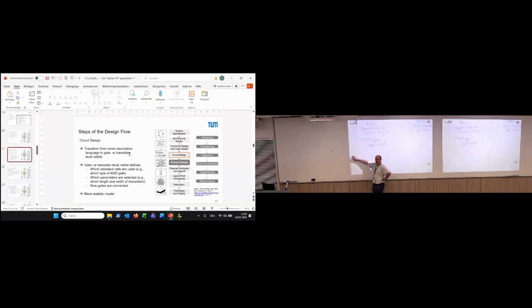So we have effectively PMOS, NMOS. PMOS: if you have a 0 at the input, you can think about this like a switch. The switch for the PMOS, if you have 0 at the input, is, think a second, is open? So it's closed, so it's connected. For the NMOS, it's the other way around. How this works on a physical level, we just ignore for the moment at least.